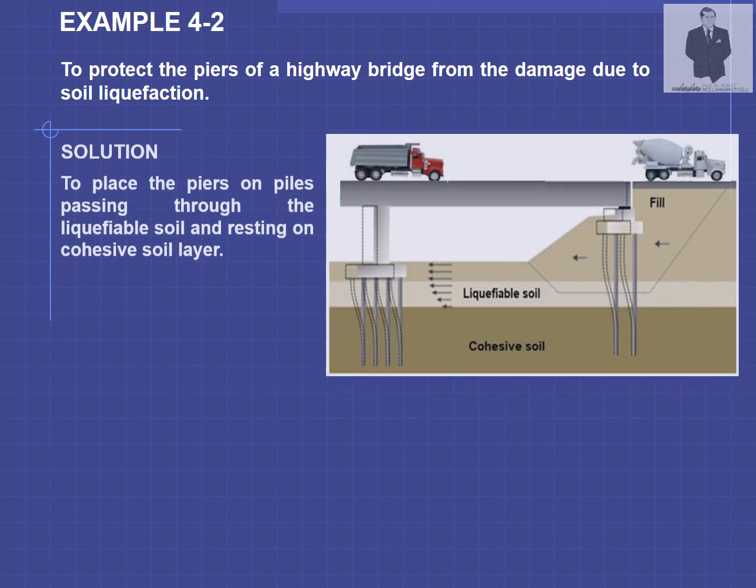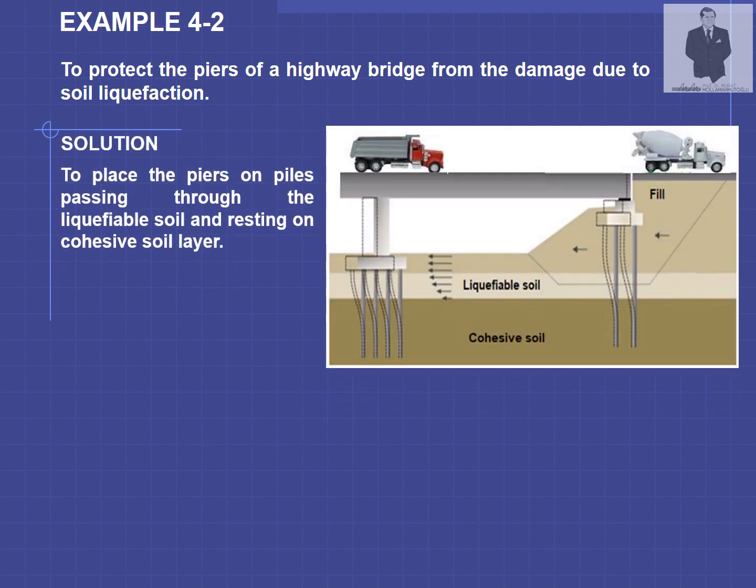In this project, the solution was to place the piers on piles, passing through the liquefiable soil and resting on cohesive soil layer, as shown here. The layer here is the liquefiable one, and you see the piles passing through and resting on cohesive soil.